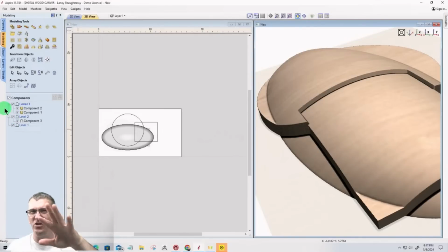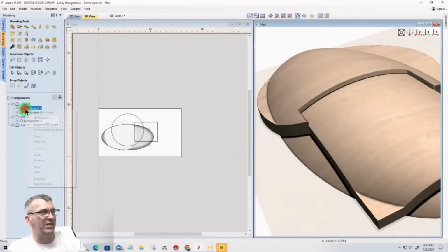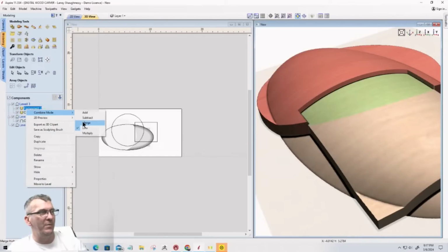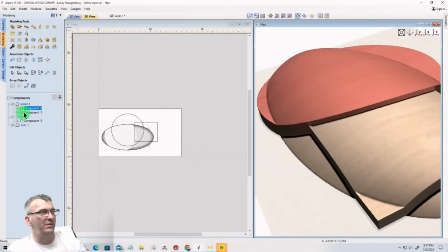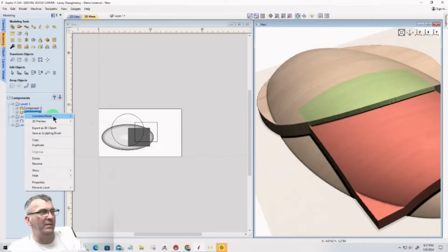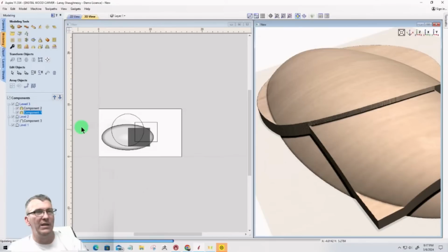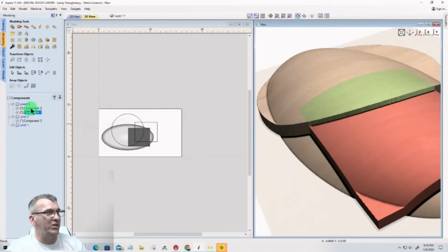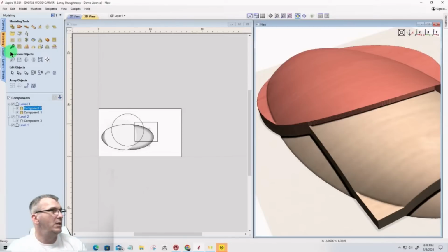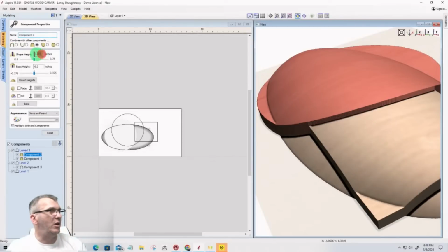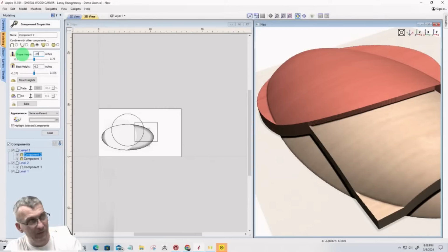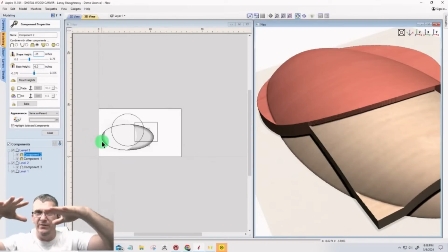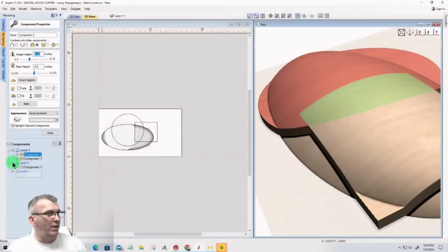Now let's make it to where there's no merge low. Let's change this to just merge. Combine mode merge. Now my rectangle and my circle are combined together. And let me change my circle size to 1/4 of an inch, 0.25. I'll change the height back to 1/4 so they're even. So now if I turn off that level 2,